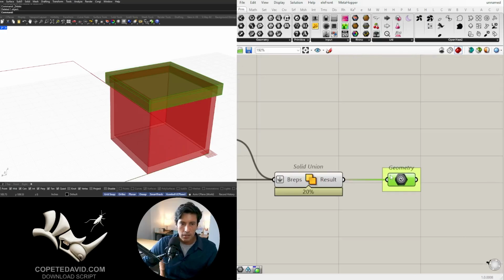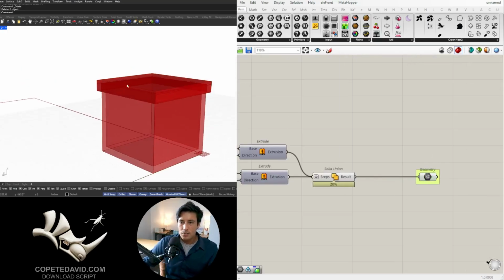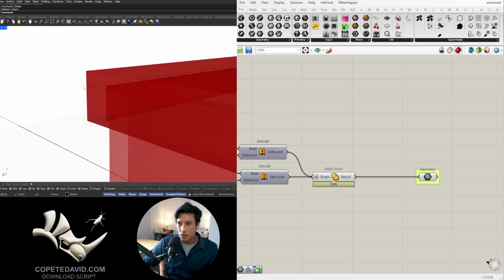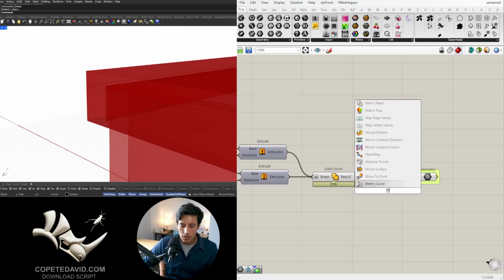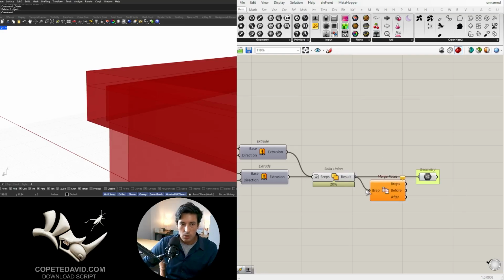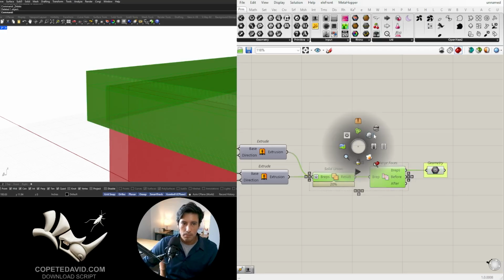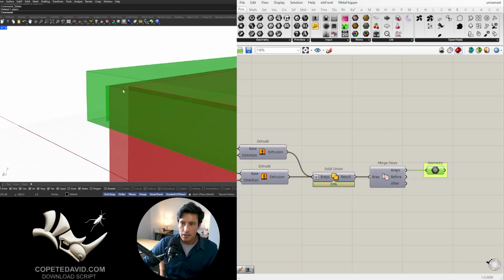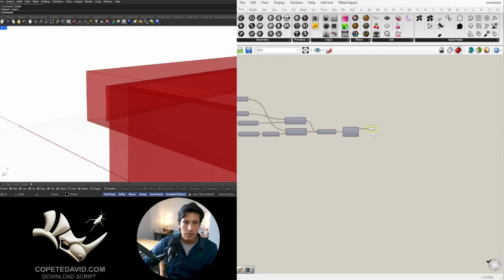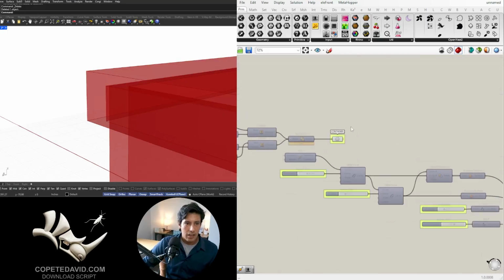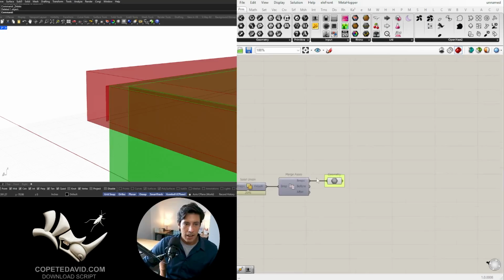This one's going to be the lid. Now here's the one thing. Notice that these are called creases where those two were joined together. I'll use merge all coplanar faces or merge all faces, and that should clean up the form. Notice that we don't have that anymore. And we have the container and the lid.